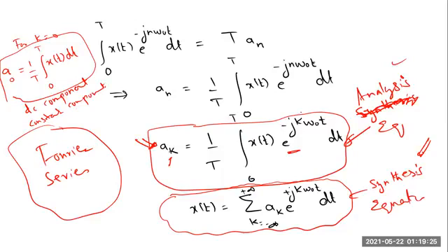So whenever you use this equation to calculate different Fourier coefficients or spectral coefficients, this special component which you get for k equal to 0 will give you the DC component that is present in this signal. And for any other value of k, if you use this equation for k equal to 1 and solve this integral, you will get the first harmonic component.